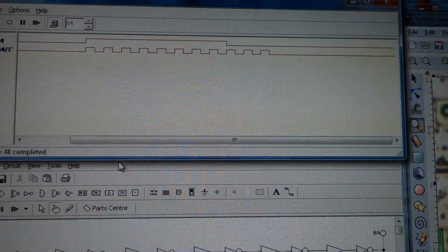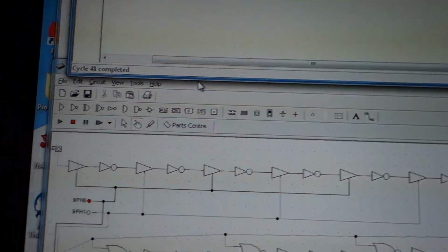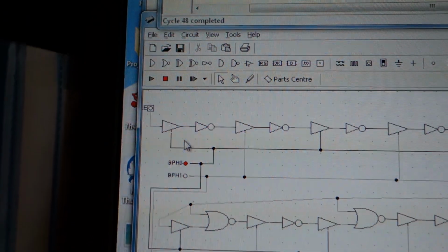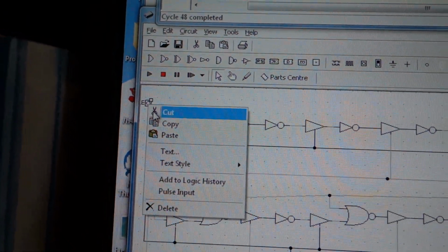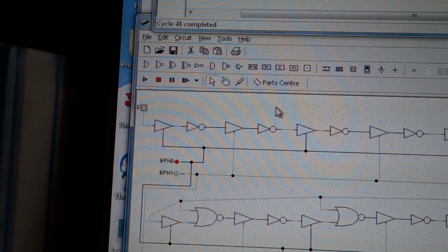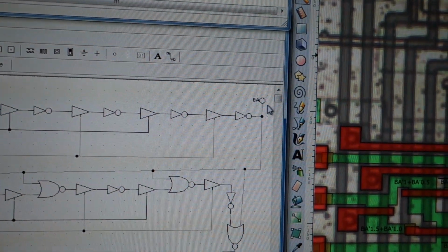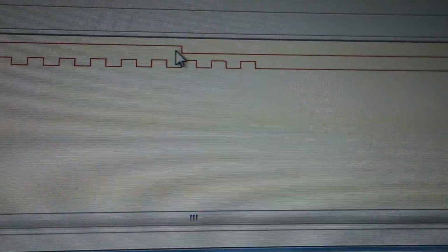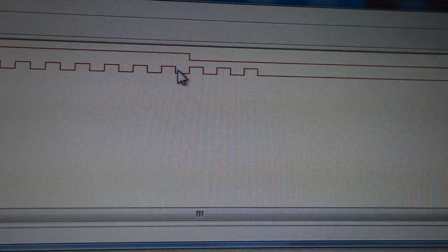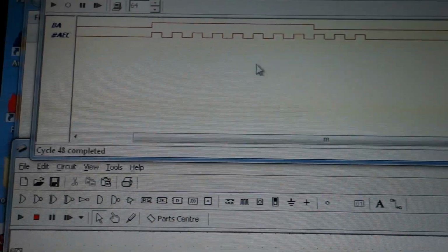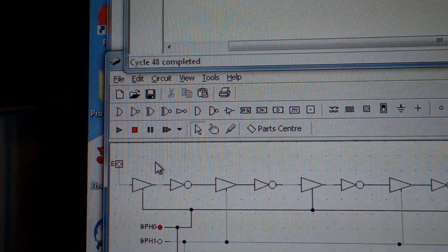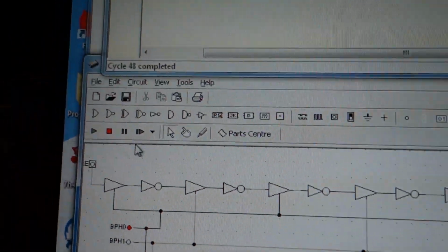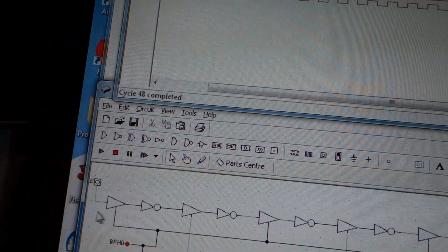Now there's one thing I haven't told you, and this is something that's used in FPGAs also: synchronization flip-flops. When I tried to do this the first time, I had a button over here, and that doesn't work so well for simulation, because when I press the button, you never know if it's in the middle of the first or second half of the cycle. So then you have something called synchronization flip-flops, which just means you have 2 flip-flops in series.